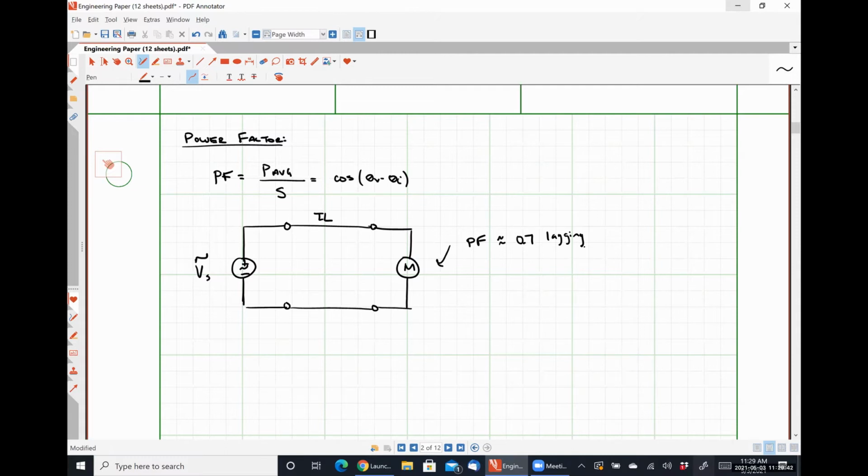set at 1. The reason why I know this is because senior design projects, some jackass always wants to measure power factor. It's boring the hell out of me because it's done every year. But they always wind up just taking fans from around the building and measuring stuff. And so at speed 3, it's somewhere around 0.6. At speed 1, it's somewhere closer to 0.9. So it's a moving target depending on how fast the motor is rotating and how much work it's trying to do and all that kind of stuff.